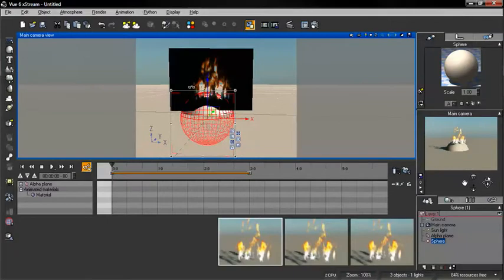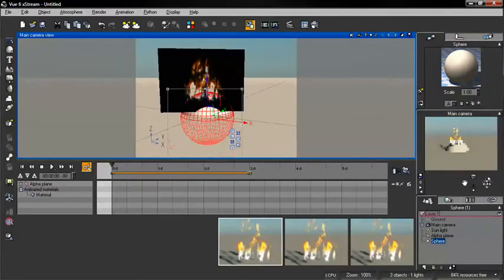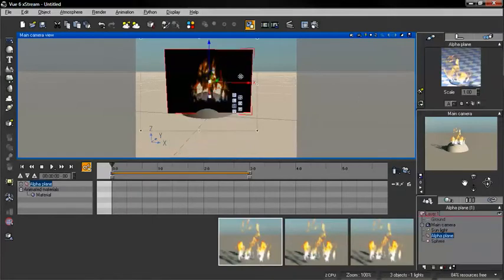And since the shadows still affect the overall scene, then it's definitely going to work for you. And since this image map is also still driven with a luminous setting rather than using the scene lights, we also have the ability to light our scenes specifically with these alpha planes. So if we're using radiosity, then the luminous factor will be taken into account, and we can actually light our scenes.